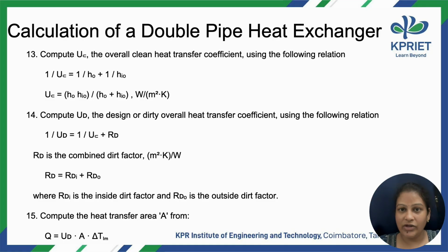So there are going to be two major differences, especially in the usage of diameter. When we are going for the inner pipe, it is important to know that for the area calculation we'll be using the inner diameter of the inner pipe. On the other hand, when we go for the annular space, for the area calculation, the diameter we are going to use is the outer diameter of the inner tube and the inner diameter of the outer tube, d2 square minus d1 square, where d2 is the inner diameter of your outer tube and d1 is the outer diameter of your inner tube.